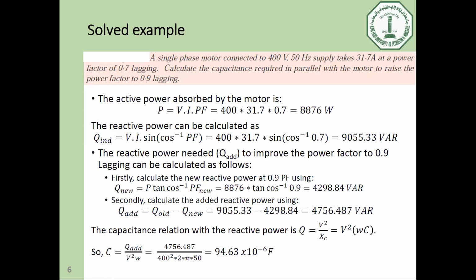By the way, Doctor, is it difficult to make the power factor unity? Sure, this is right, but why? Anybody know? Why is it not easy to reach unity? Maybe because of transients. Because of the load changing, this is one important thing. The other thing is the existence of harmonics in our systems. Harmonics reduce the power factor.